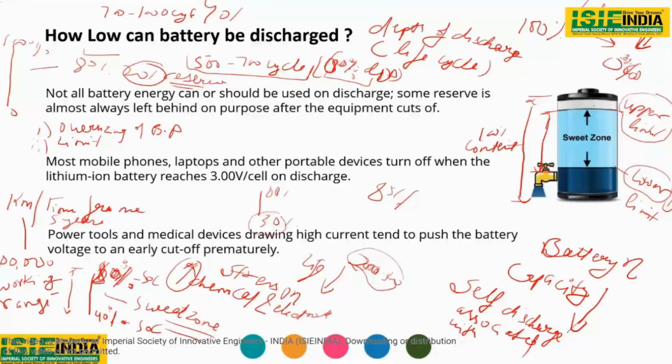So that's why it is always advisable to keep some residual charge inside the battery. Do not completely discharge your battery pack. Always keep some charge inside your battery. As it is written here, not all battery energy should be discharged. Some reserve is almost always left behind on purpose. And there is a voltage cutoff.